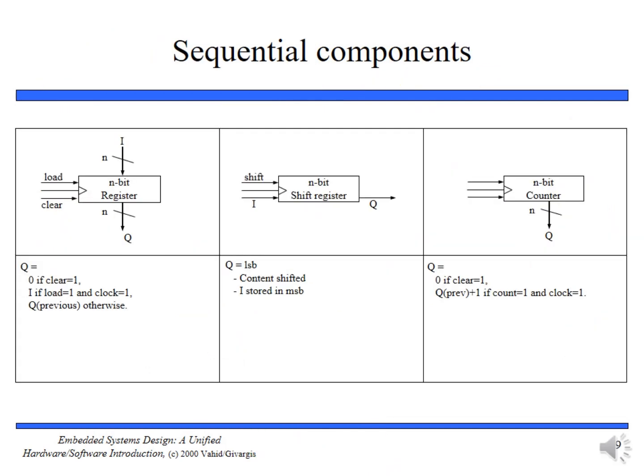So when we talk about sequential logic, one thing that appears in mind is flip-flop. A flip-flop is a sequential circuit whose outputs are a function of present as well as previous input. So now the difference between sequential components and combinational components can be clarified: in sequential components the output is a function of present as well as previous input, whereas in combinational logic the output is a function of only present inputs. In other words, sequential logic possesses memory.